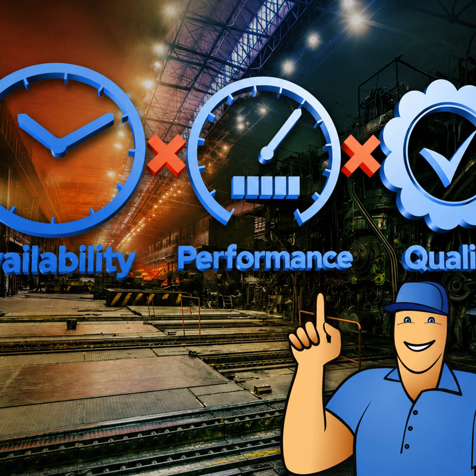The blame trap. The fastest way to kill OEE tracking is by using it to punish people. Post-shift rankings. Tie bonuses to OEE. Publicly call out underperformers. Watch what happens. Operators stop reporting downtime. Adjustments get called planned maintenance. Quality issues disappear from paperwork but show up with customers. The cost. People game the numbers instead of fixing problems.